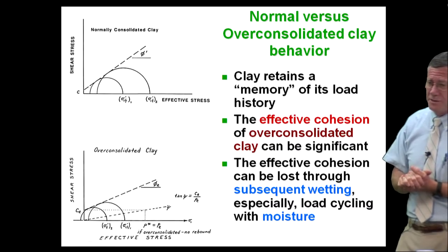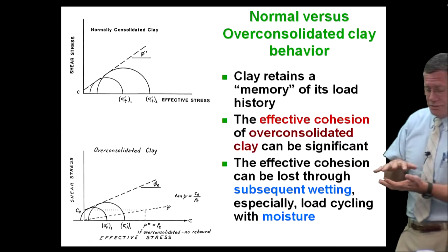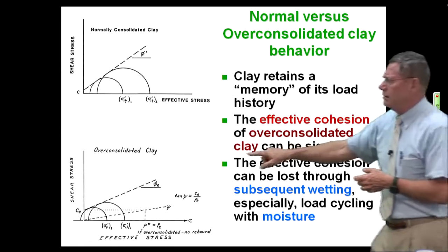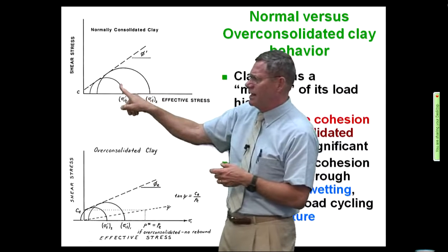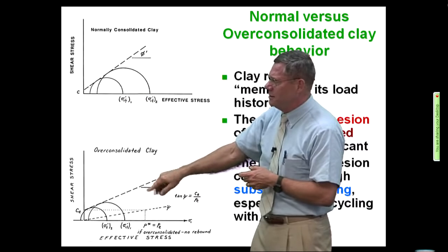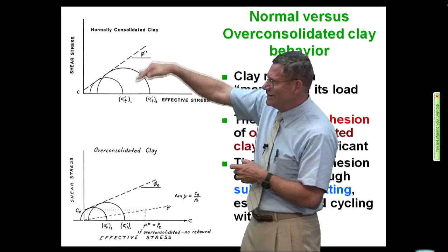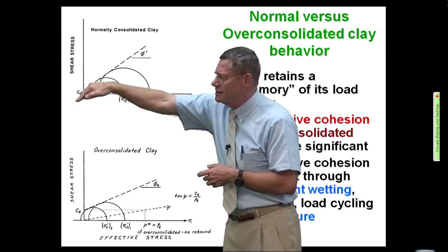you're going to get a whole different answer. Whole different answer. Because you're getting pseudo drainage while you're shearing. And you're going to have this kind of a diagram instead of that kind of diagram. And you notice the phi angle here is a lot lower than the phi angle here of the rapid shear test.